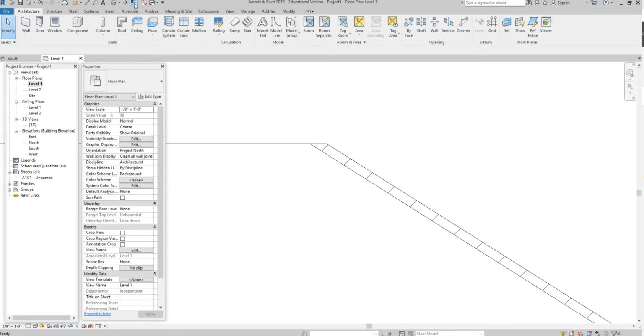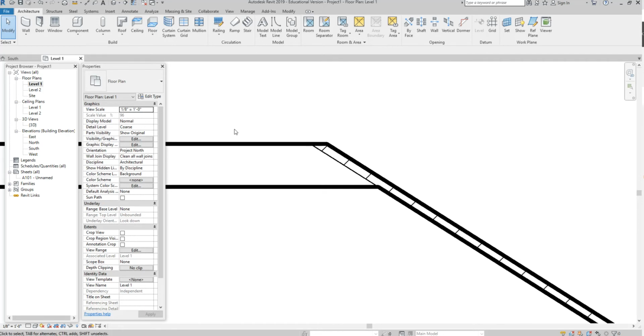Click, click. There's also a keyboard shortcut, TL, which I use probably more than anything, that will allow me to remove that graphic representation. Now, if I were to print, it doesn't physically take it away, right? So the line weights will always print. Thick lines look thick, thin lines look thin, always when I print. But I don't have to view them on the screen if I don't want to.